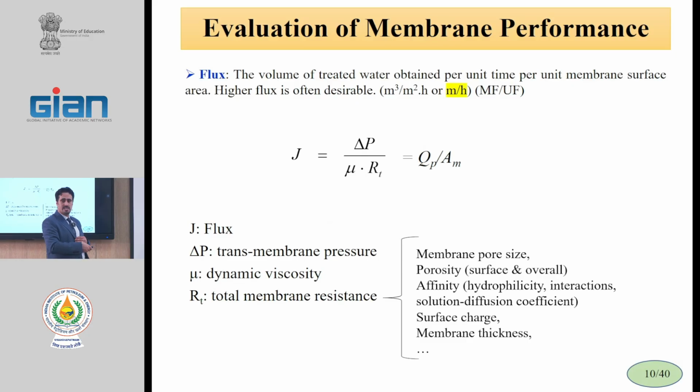Porosity. Porosity is the free space in the membrane body or in the membrane surface. With the increase of porosity, resistance reduces. High porosity, high flux.